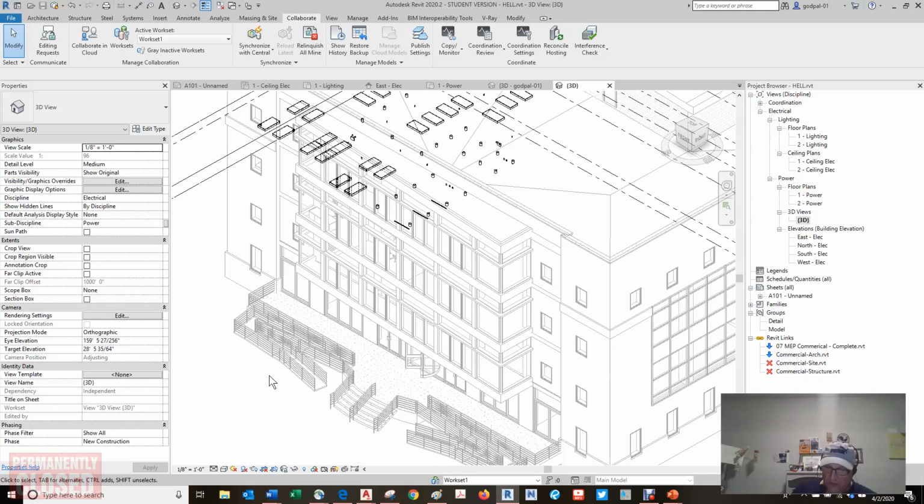Most modeling tools and commands require an active work plane on which to place geometry. When you are working in a plan view, the work plane is usually set to the current level associated with the view. In a 3D section or elevation view, the definition of an active work plane may be a bit more confusing.